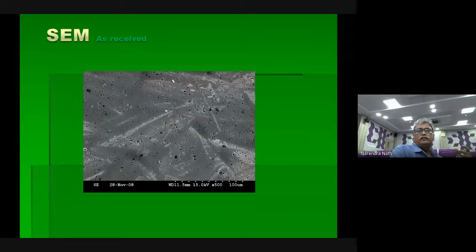And this is actually very typical. Titanium nickel is very typical. So whatever you are seeing here, these are all not holes. These are all precipitates. Precipitates look like this. Because of polishing, they get pulled out and it looks like a porosity, but it is not the case. This is because of our poor polishing and etching. So wherever you are seeing that, that is not the case.